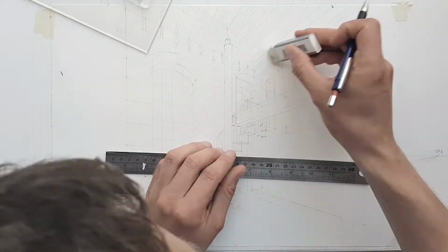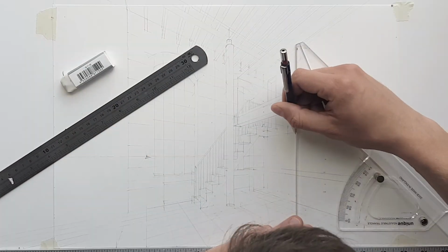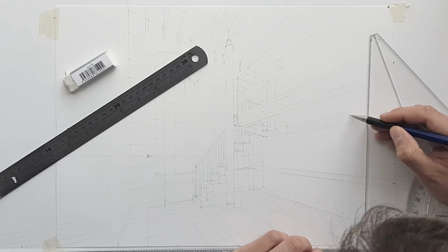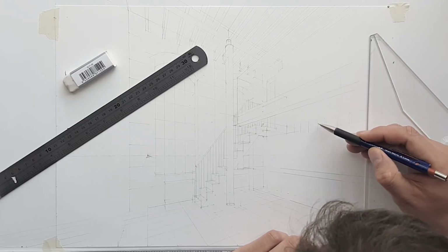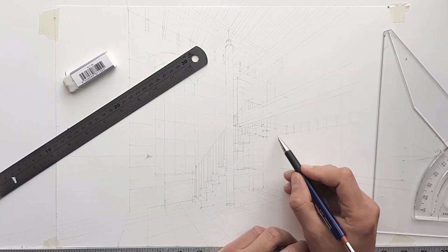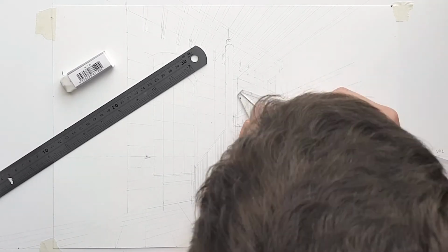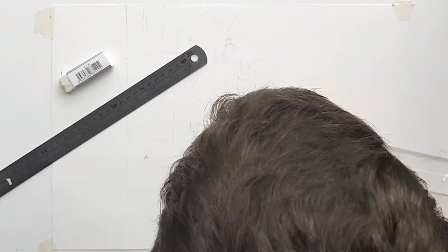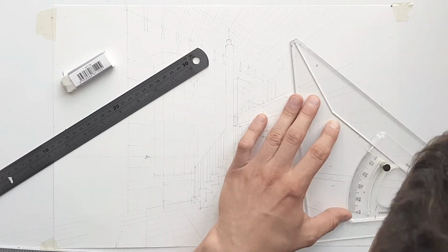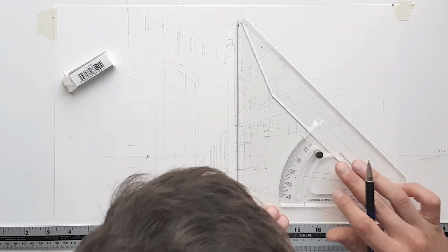So once we have the railing drawn, we can now erase the back lines a little bit to make them less intense, and midpoints of timber beams under the mezzanine are pulled up from the increment divisions on the ground plane along the right hand side wall, and similarly to the way we did them on the ceiling, I'm adding the thickness on either side. I also project these midpoints towards the I-beam to act as base points for the railing.